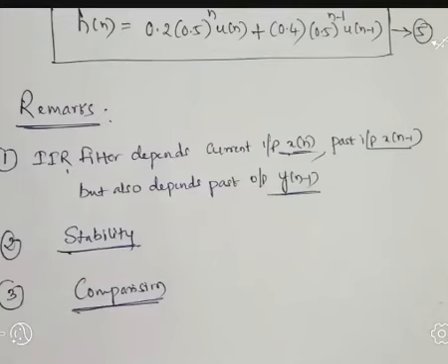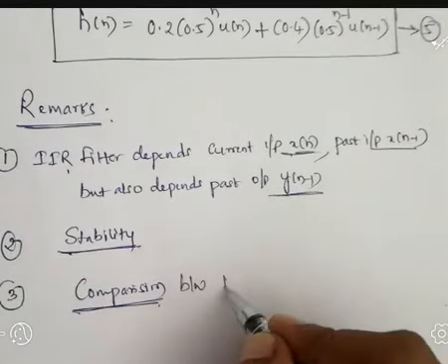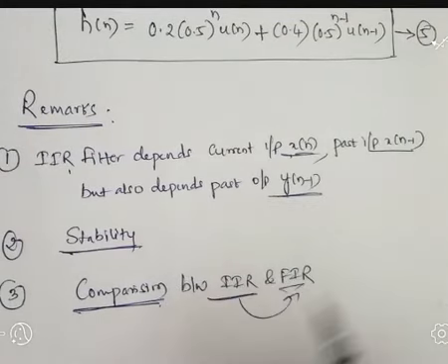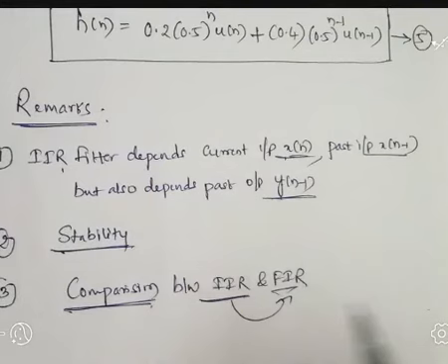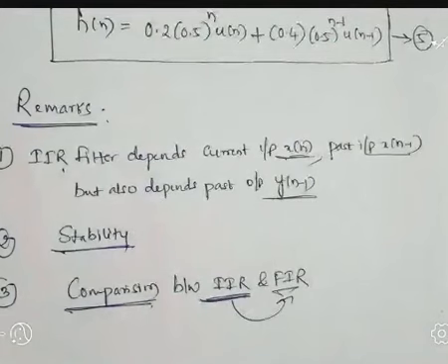Comparing with that, compared with the FIR filter, the IIR filter offers a much smaller filter size. Hence, the filter operation requires a fewer number of computations, but the linear phase is not easily obtained.